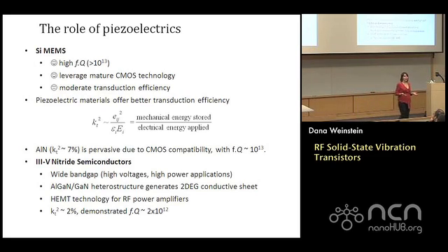It's wide band gap, right? It's similar in performance to aluminum nitride, except it's a semiconductor, and I can get these HEMTs, high electron mobility transistors, built into it. And that leverages 2D electron gas, right? That forms the channel of the transistor in a GaN-AlGaN heterostructure. So that's the typical gallium nitride transistor, looks something like that.